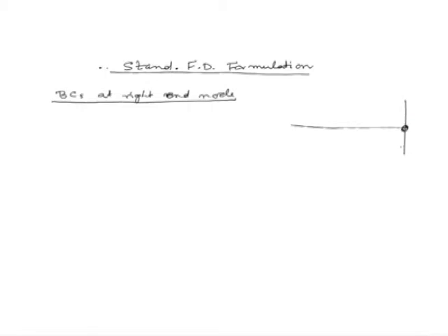This is our grid point and its index would be n plus 1 if your number of divisions is n. The node next to it will have an index of n and so on. Boundary conditions would be specified here. So let us have three cases. The first one is our BC type equal to 0, where we simply say that Tn plus 1 is specified as the given boundary temperature.